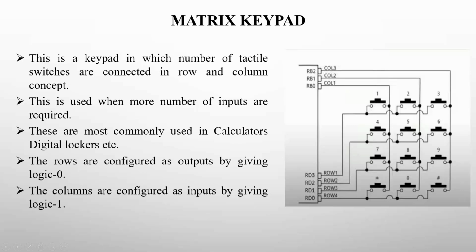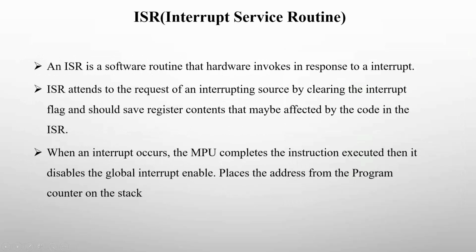Basically, in our project, we are using PIC16F877A microcontroller. Port D is connected to rows and port B is connected to columns. And the rows are configured as outputs by giving logic 0 and the columns are configured as inputs by giving logic 1. And coming to interrupt service routine, interrupt service routine means